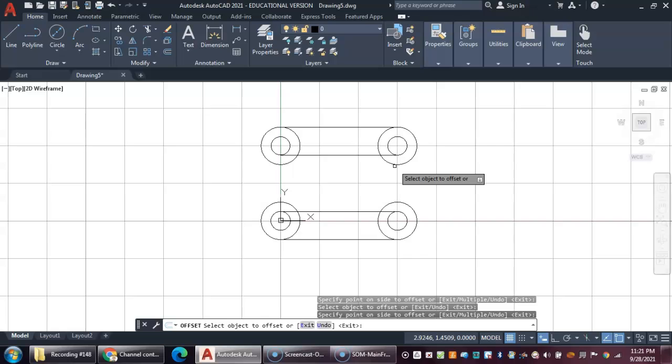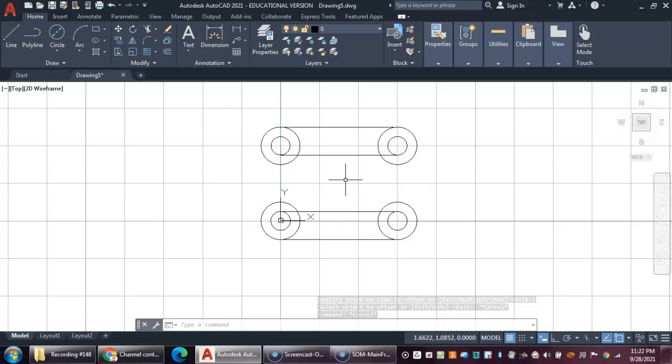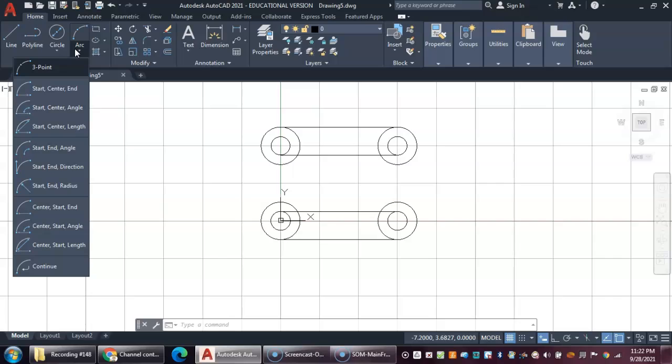Now it's kind of a matter of going through with some arcs, and we got to stop to think about. Let me escape out of the offset tool, and I have two 3-inch radius arcs that are on the outside. And if we take a look at those, we can see that those arcs are tangent to these curves, to these larger diameters. So let's go and see if I've got any type of arc that might give me a tangency point.